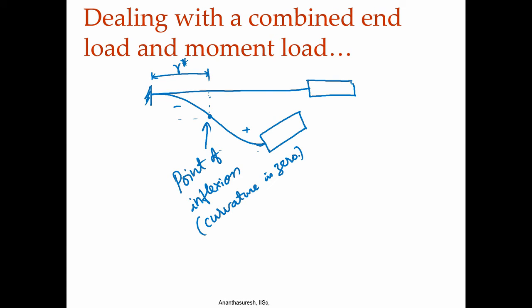That gamma star changes from position to position. In one mechanism it is constant, we can get it and be done with it, but that is not the case. As the mechanism moves, this gamma star will also vary, and then we will have an extra parameter. We have gamma star as a parameter, and then we have a cantilever beam, the slope at that point, which will be the same for this part of the cantilever beam and the other part, left side and right side. Then there will be another parameter, and that is what we need to do.